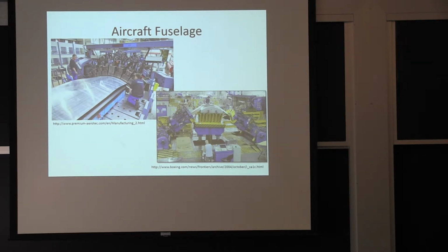But if you stretch something and everything is plastic, you let it go, it tends to be exactly the same. So for thin members in aircraft fuselage, it is the most common process. You can do a double curvature relatively easily, and the stretching operation also helps you with the heat treatment. Actually, we'll go through the heat treatment of aluminum next week.